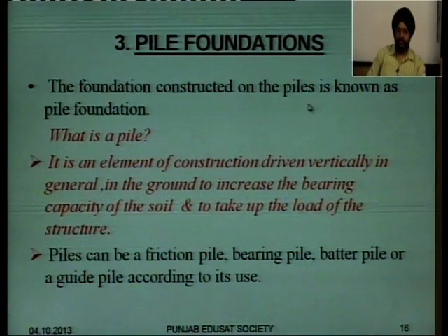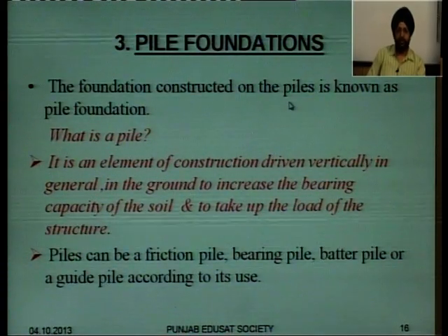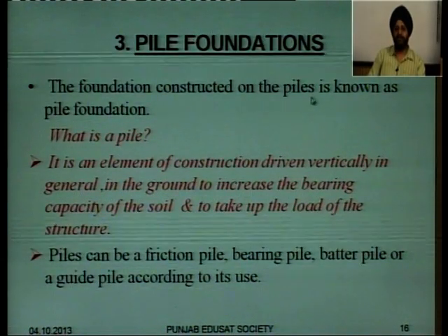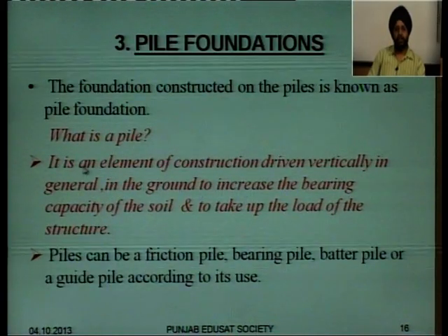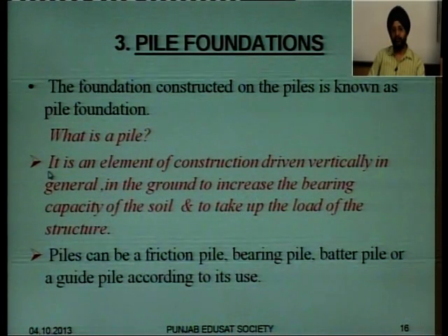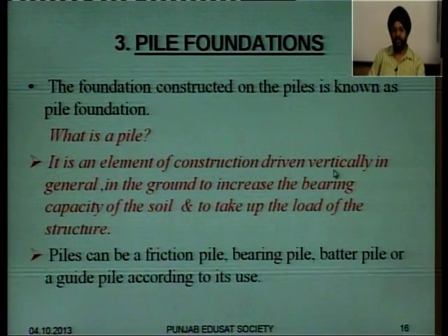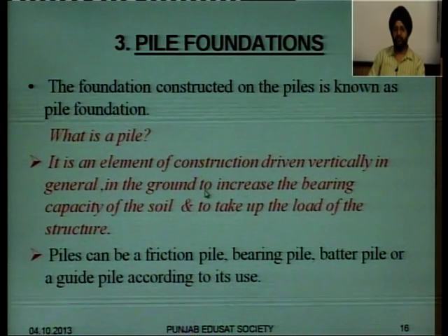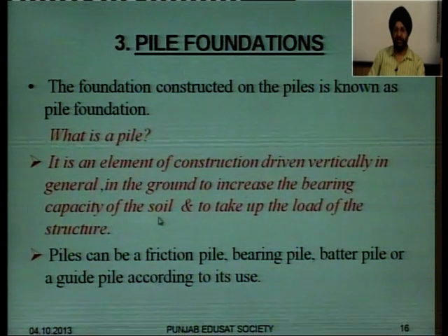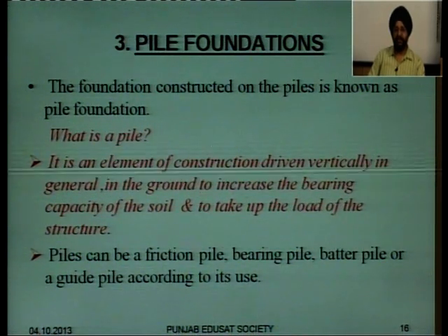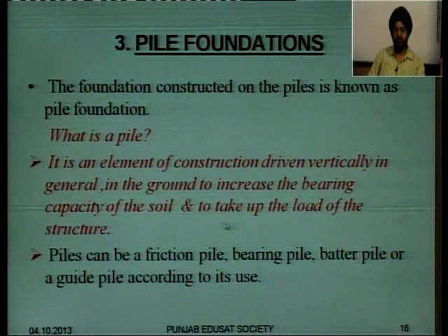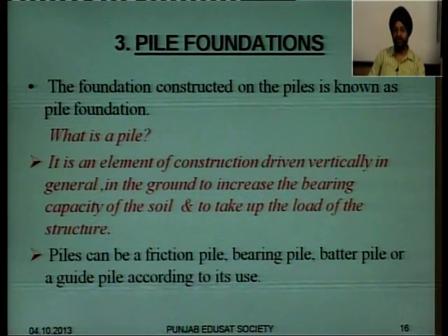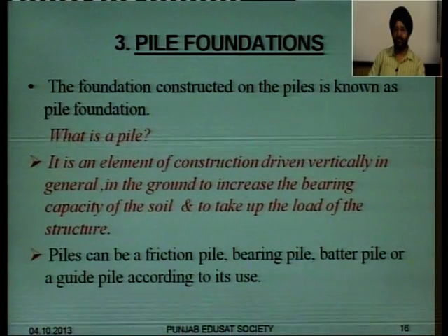Let's have a look at this particular term, piles. Now what is a pile? Before studying pile foundation, I would like to concentrate on this term. A pile is an element of construction which is driven vertically in general, deep into the ground to increase the bearing capacity of the soil and to take up the load of the structure. After watching the diagrams, you will get a clearer idea how piling is done and how it increases the bearing capacity of the soil.